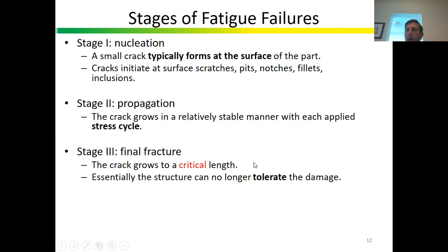All right, so we just want to talk about the progression of the damage when it comes to fatigue, because we want to look at maybe both the macro and the microstructural features. So what happens with fatigue loaded parts is at first usually you assume the surface is pristine or in really good shape. It's polished or it's got no real big tooling marks or anything like that, no big large scratches or gouges. But over time, what happens is, especially if the part is subjected to bending, we know that for the bending stresses, the largest stresses are on the outermost fiber, so it's no real surprise that that's where cracks start to, what they call, nucleate or grow.